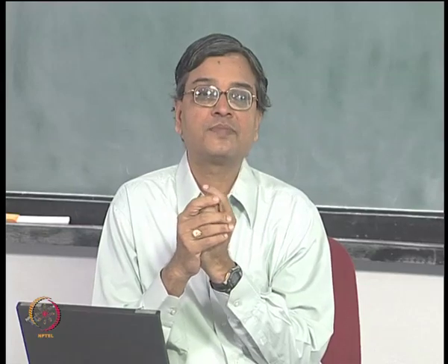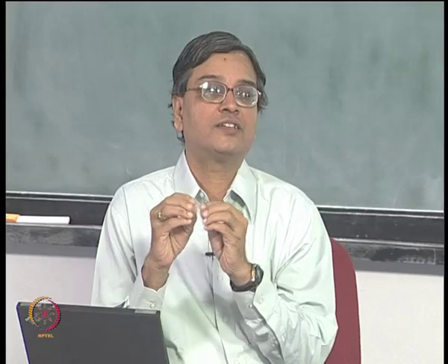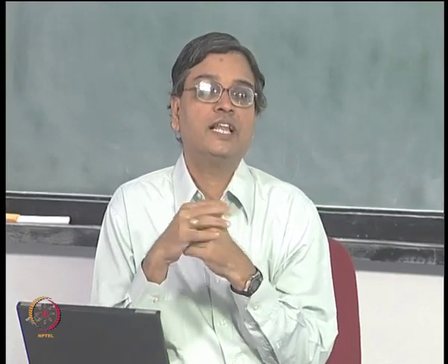But what I will do now is, you take my word for granted at this stage of the course, and in the present example the contours observed are isochromatics depicting contours of principal stress difference. And for you to understand this, we have to develop crystal optics. Nevertheless, if time permits, towards the end of this lecture itself, you will be able to appreciate from a solid mechanics point of view how one can say that these contours are sigma 1 minus sigma 2 contours.